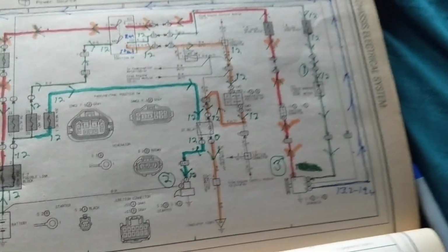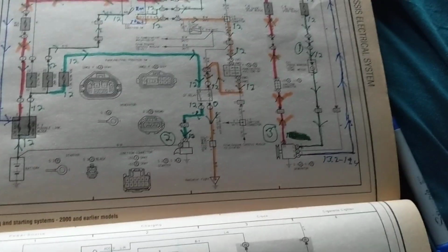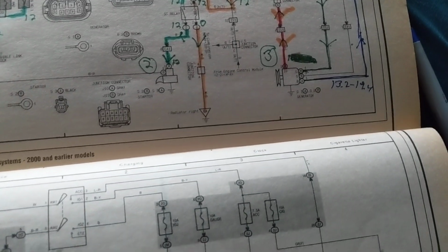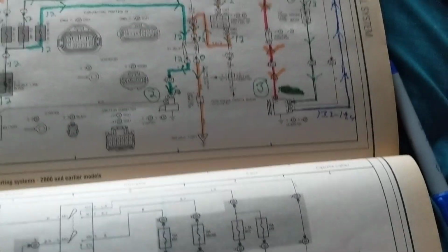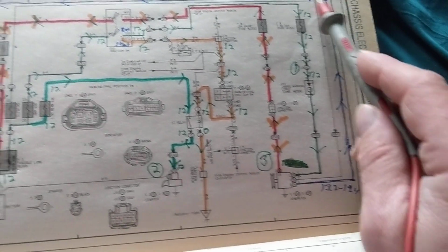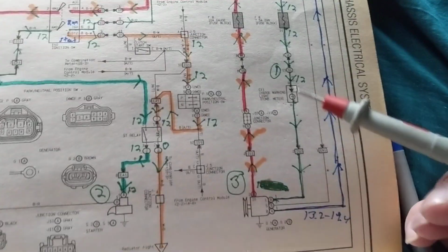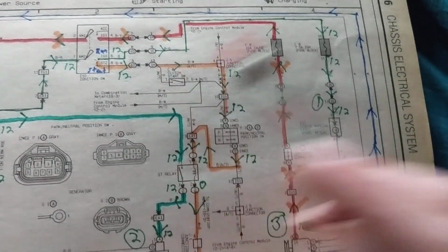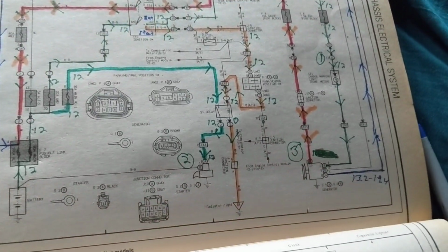Once you start the starter motor, then you crank the engine. When you crank the engine, the pulleys turn, the serpentine belt turns. Very important. And the alternator starts creating its AC, which is rectified to DC. That DC comes out here, through here, through here, through here. You see that. Then what happens? Finally, when we go back to the run position, guess what? Now, the light goes out. All that happens in run and start position.